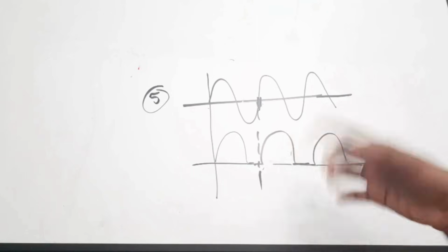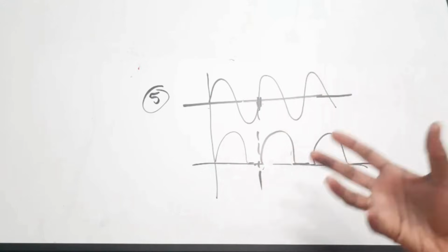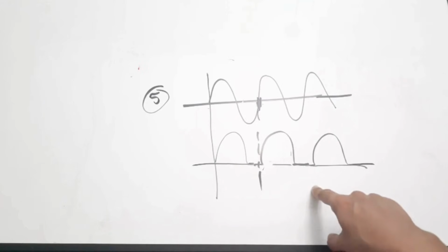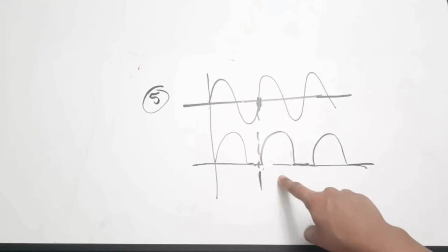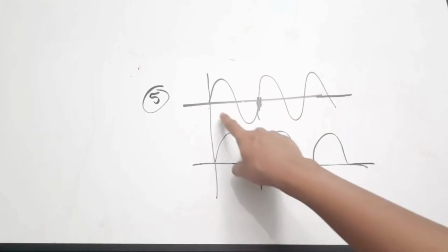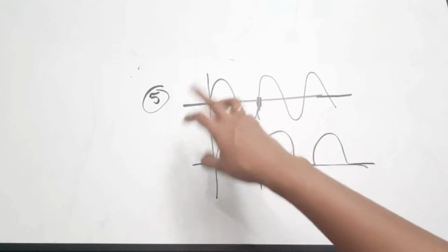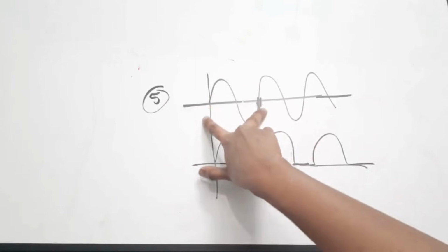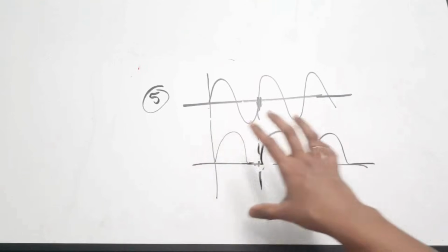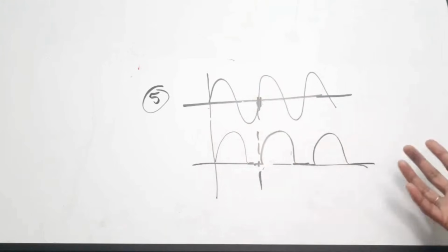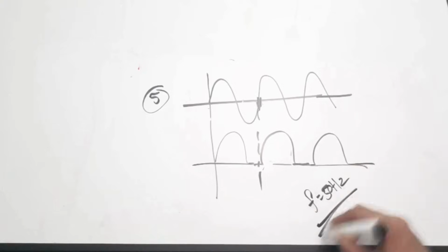So here the question, I don't want to confuse you. The question is, what is the ripple frequency of a half wave rectifier output? If the input frequency is 50 hertz, the output frequency is exactly the same, because in this cycle the full wave is passing over one wave or one cycle. The frequency will be exactly the same. Here also one half is passing. So the rectified version also, the frequency is exactly the same. So f equals 50 hertz will be the ripple frequency also.